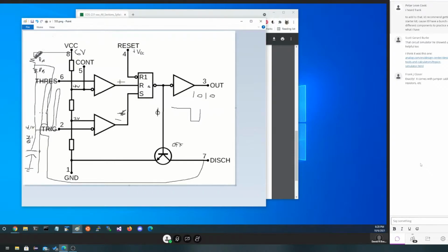We could make this very, very tiny, and then this would be nearly a 50% duty cycle. But normally we don't do that. We try to keep within the range that the data sheet showed us in that chart because the chip has been shown to operate best in that range. And if you needed 50%, there's better ways of doing that anyway. You wouldn't just use this chip, you'd use a secondary chip as well.